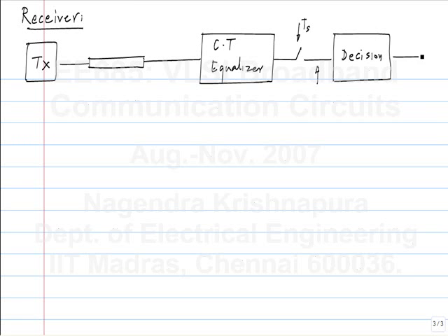In addition to this, a receiver also will need to determine the clock that you need for sampling. Because you know the frequency approximately, and even if you know the frequency exactly, you don't know the phase. In the transmitter, there is an oscillator which creates a clock which causes the symbols to be transmitted at a certain rate. And in the receiver, you have a physically different oscillator. You can never make the frequencies of the two exactly the same. So you have to have some method of controlling the frequency of this so that it turns out to be equal to this one. And also the phase should be correct.